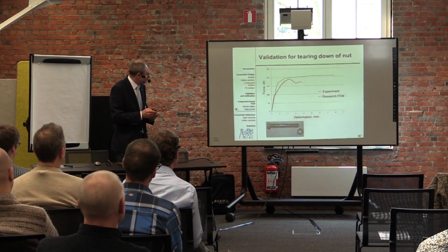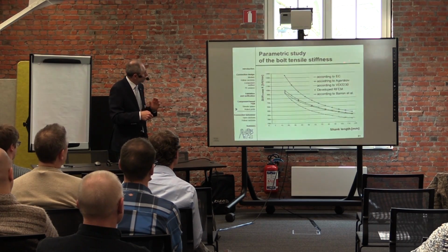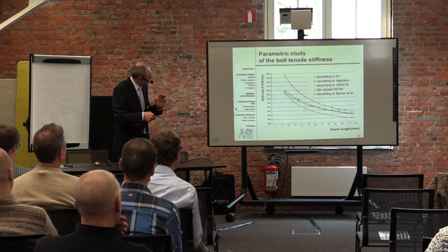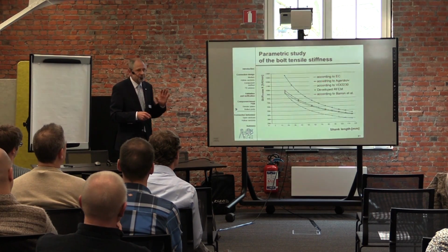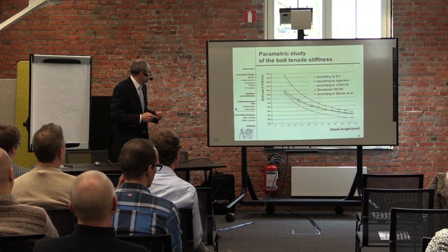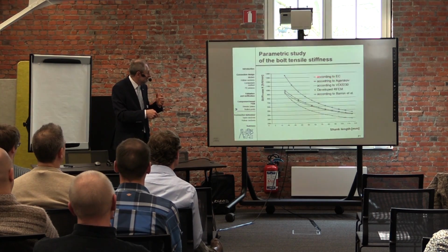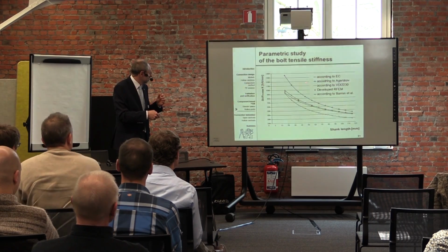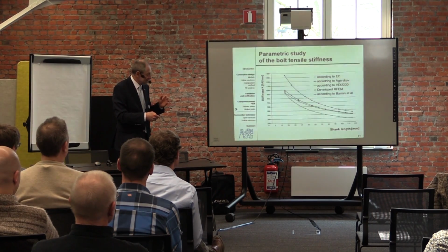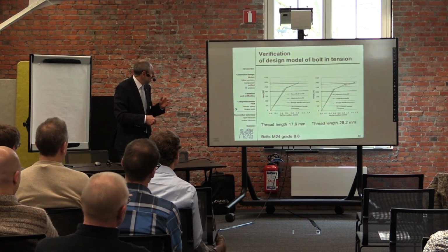And then we observed from literature already. Agerskov, my professor in Denmark, did some study about the stiffness of the bolt because it has an influence on the connection behavior. And finally, we also have the Eurocode prediction of stiffness, and it's rather good. So we verify this against Eurocode. Here you see our results.